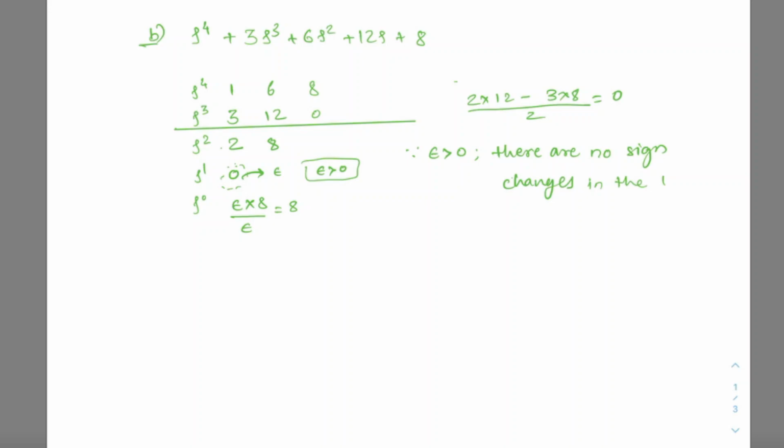So let us start with the first part, a P controller. For such a controller, C of S is Kp. So G of S, which we had previously defined as P of S into C of S, is Kp over S square plus 4.